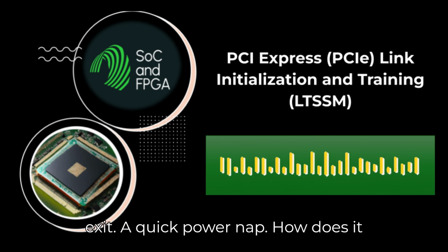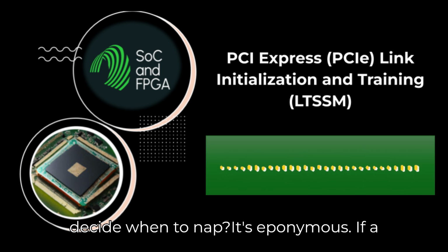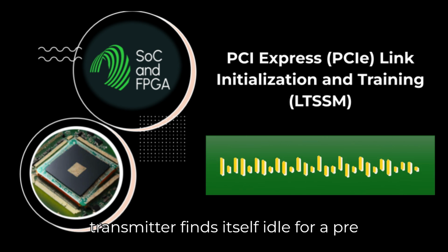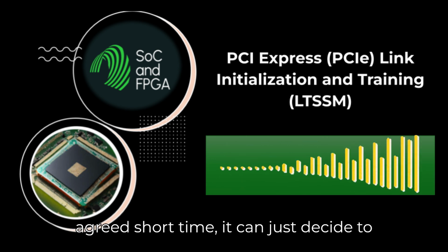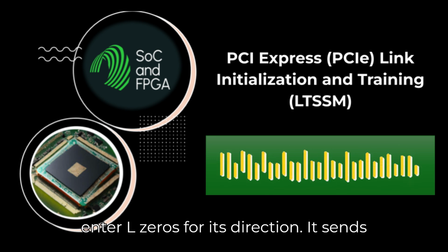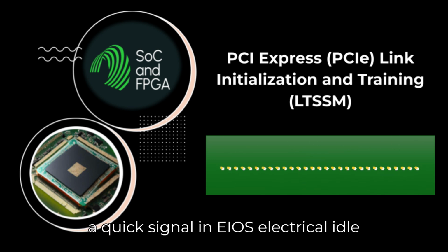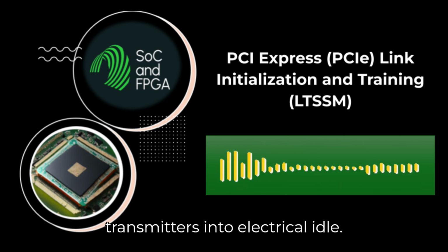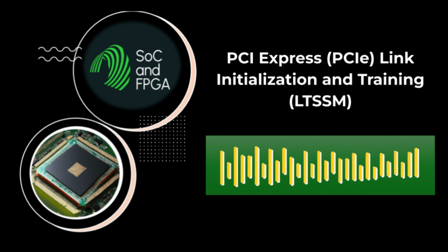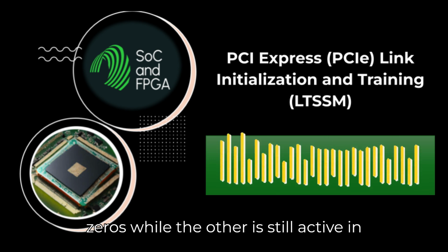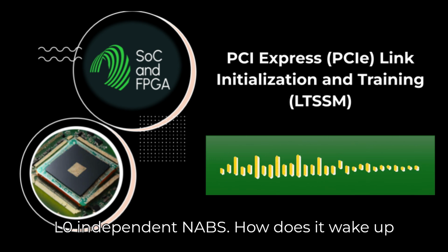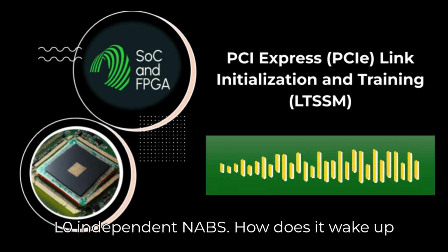A quick power nap. How does it decide when to nap? It's autonomous. If a transmitter finds itself idle for a pre-agreed short time, it can just decide to enter L0s for its direction. It sends a quick signal, an EIOS, electrical idle ordered set, and then puts its transmitters into electrical idle. Importantly, one direction can be in L0s while the other is still active in L0. Independent naps.